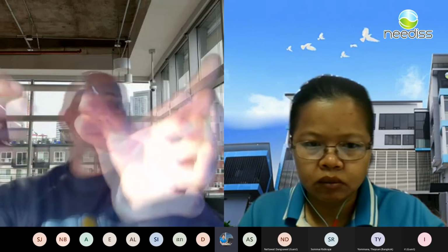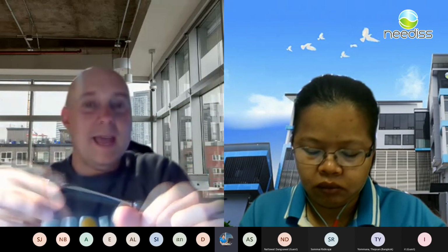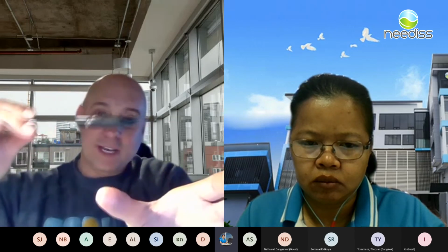Another good way to determine if you have cyclonic flow or bouncing flow is if you've sampled this location before and you are sampling points 1, 2, and 3 across the stack, and you move your Method 5 probe to location number 4, and all of a sudden your delta P reading goes really high or really low compared to what the delta P was on the other side of the stack.